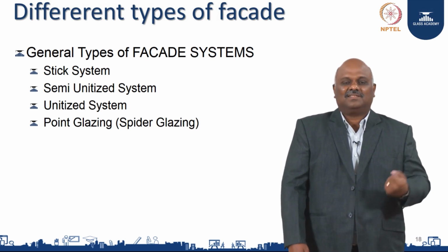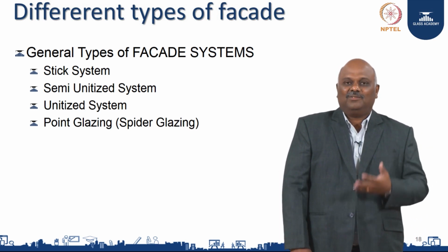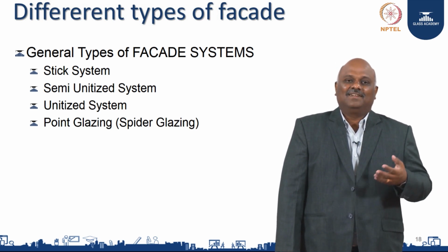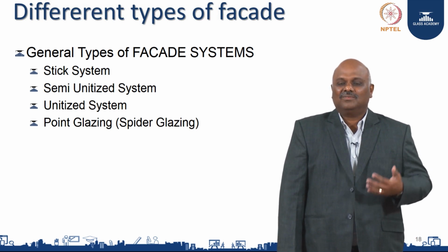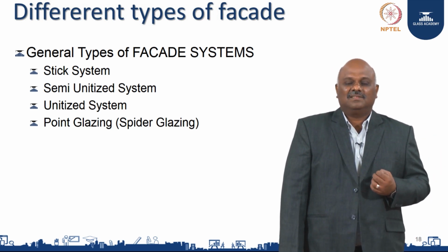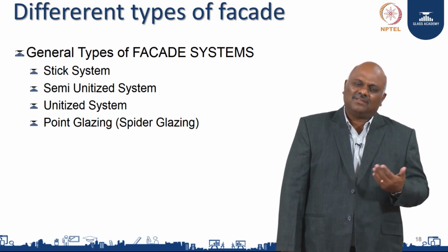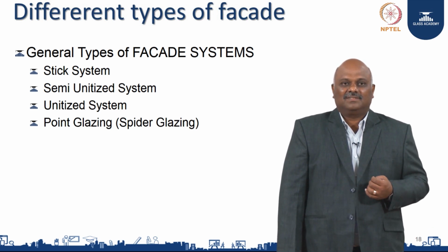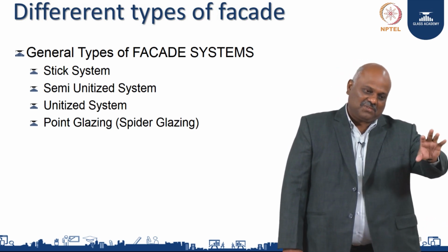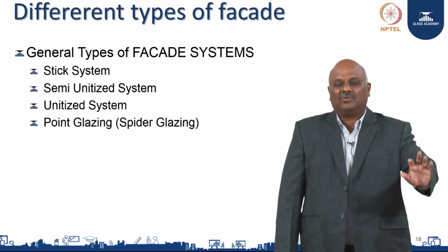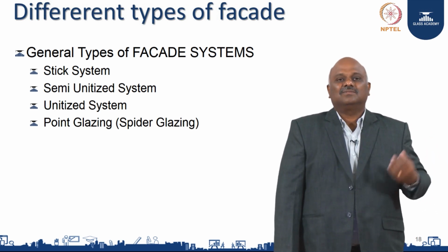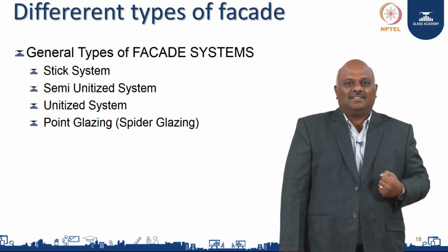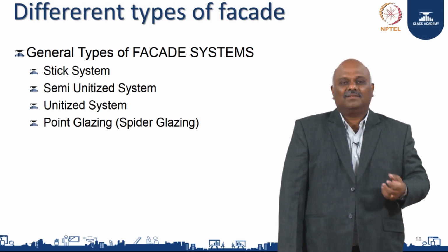How do you do that? It is labor intensive. And when you design such big buildings with the stick system, they don't perform unless you have a system which can take care of all the impact. So the invention came into place. Yes, they still practice the stick system in certain parts of the world, but it's almost taken out of the facade field. You can use it maybe in small buildings with one floor or two floors, where you do some small work that doesn't have too much impact from nature. There we can start using it.